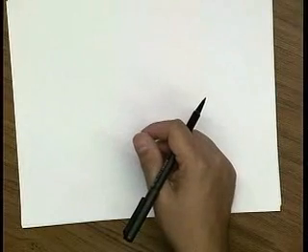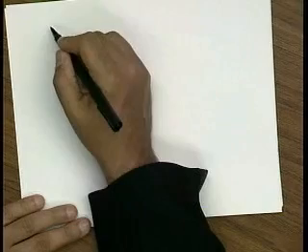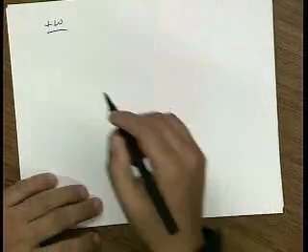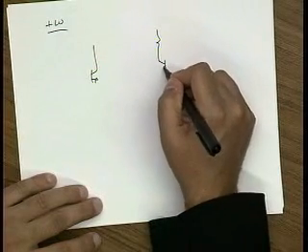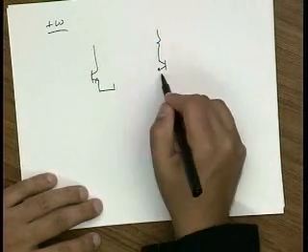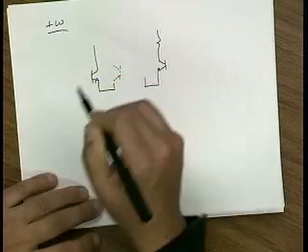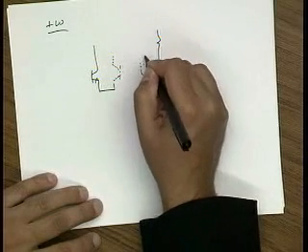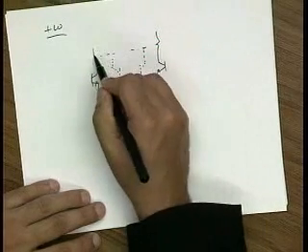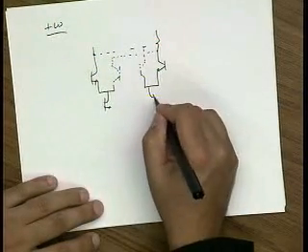So let's see how this circuit works. So let's draw the signal for different RF. So let's go for a plus LO. So for a plus LO, the two outer transistors are on. And these devices are off. Okay. And this is our diff pair.